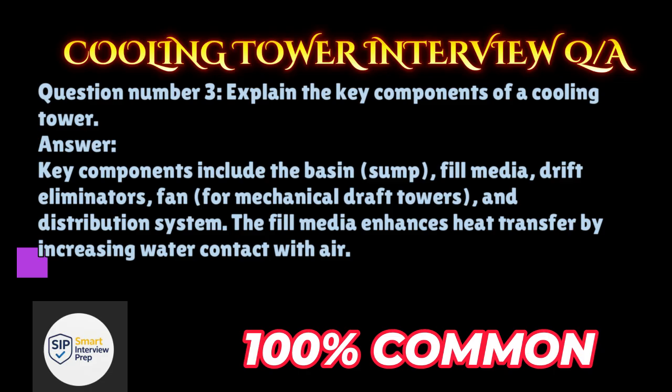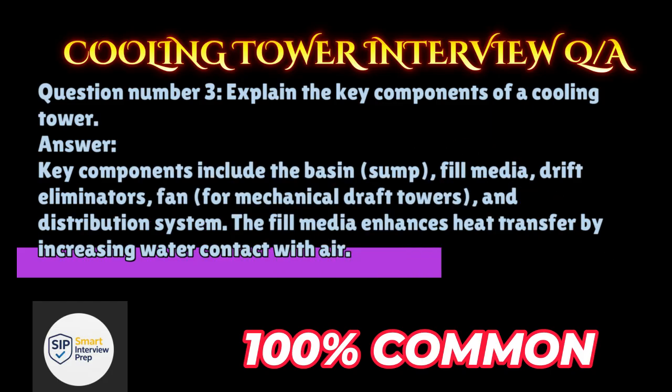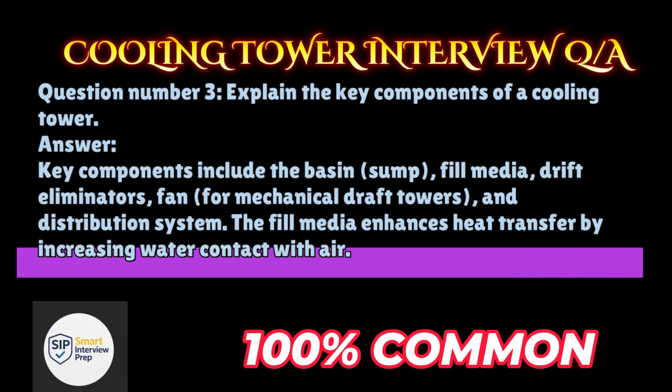Question number 3. Explain the key components of a cooling tower. Answer. Key components include the basin, sump, fill media, drift eliminators, fan for mechanical draft towers, and distribution system. The fill media enhances heat transfer by increasing water contact with air.